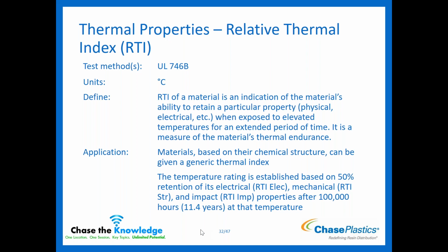The other thing to note, and it happens quite a bit, is that sometimes the suppliers won't have the RTI tested for their particular materials, so they are able to be given a generic rating based on that type of material. If I took this Ultem and they didn't want to have it tested specifically and pay for the testing, because it's very expensive, it takes a long time, about 2 years, and can cost hundreds of thousands of dollars to have the testing done, they can be given a generic rating.